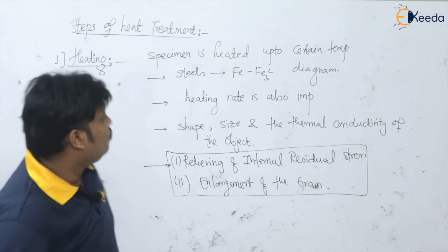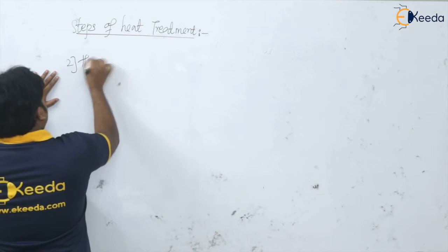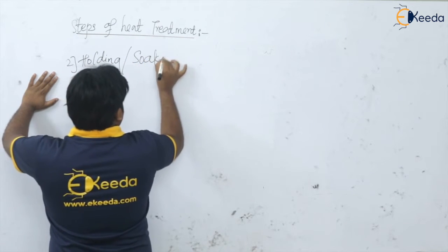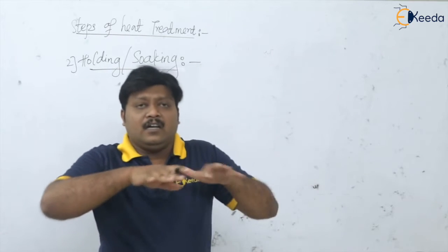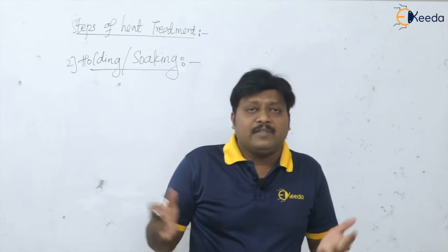Let us see about the holding or soaking. The second step is holding or soaking. After heating, the specimen is held or soaked for a particular time period.